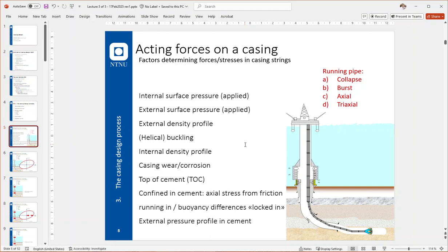That's kind of following what we call the worst case scenario, and that's what we always do in casing design, thinking worst case scenario. We can just jump on and talk about cement immediately. Cement, when you're pumping it, as said, the density itself has an effect, direct, and that's one situation that we need to do as an analysis.